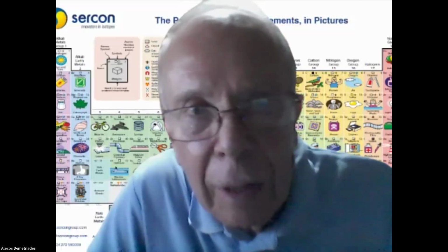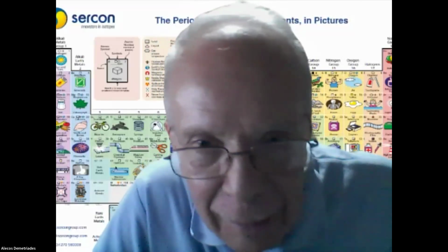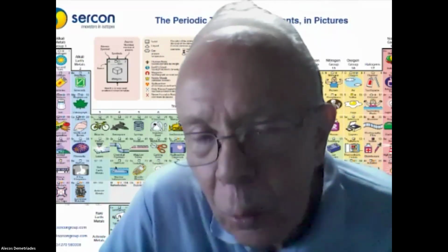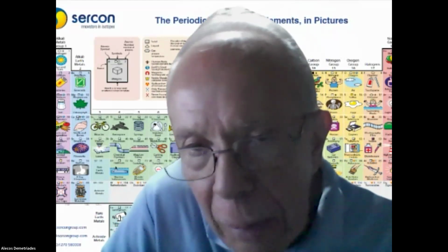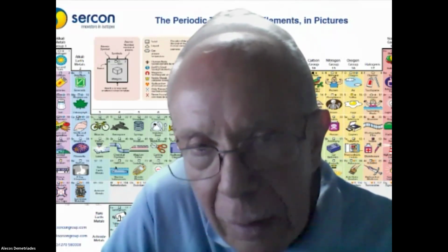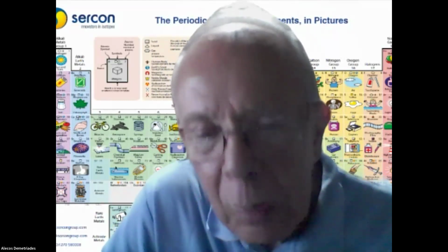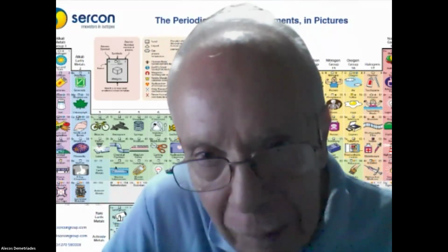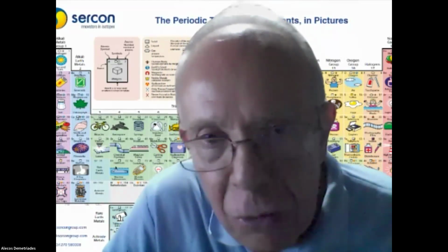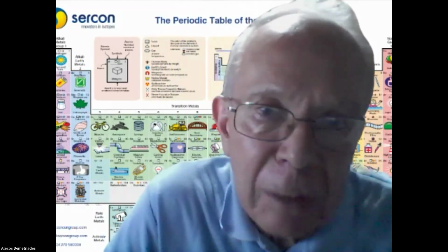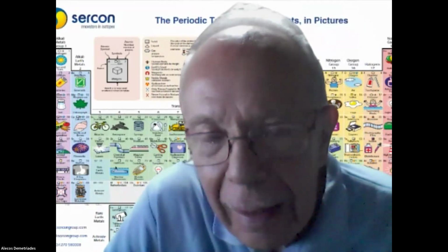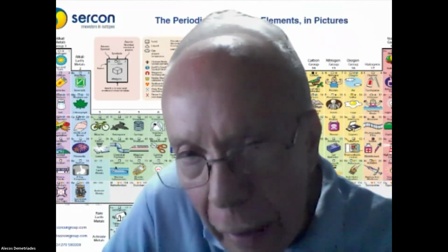Yes, that's more complicated, David. That's the problem. That's why you need to carry out, this is what I strongly believe in, an orientation survey to begin with. Because the orientation survey will give you all the elements that you need to plan the detailed investigation more correctly.